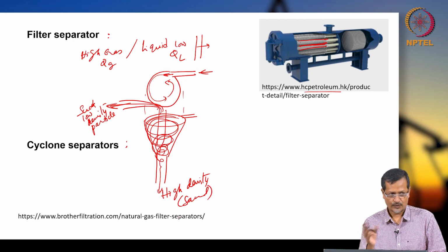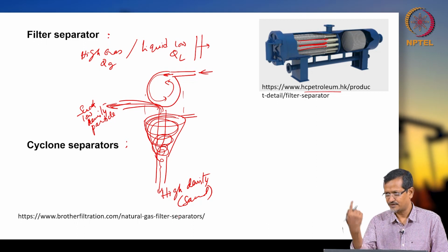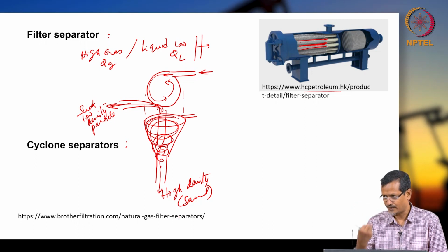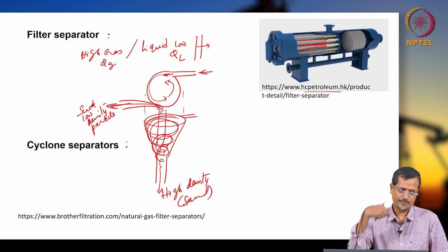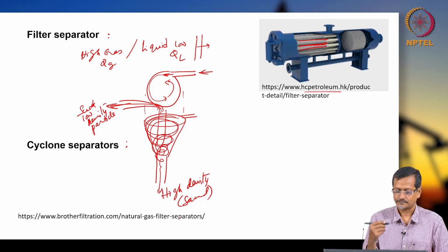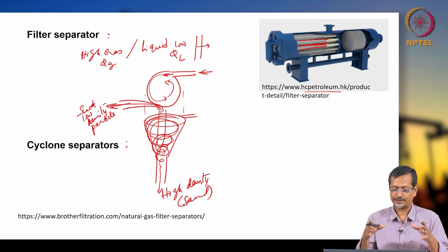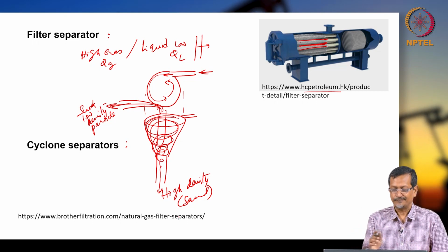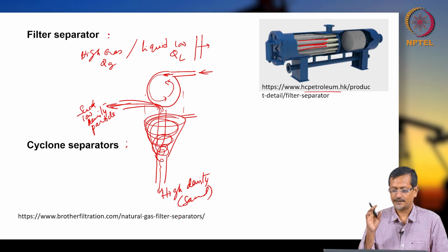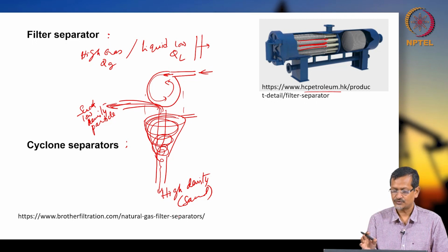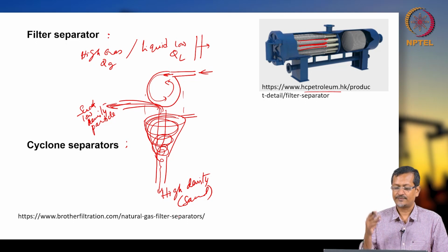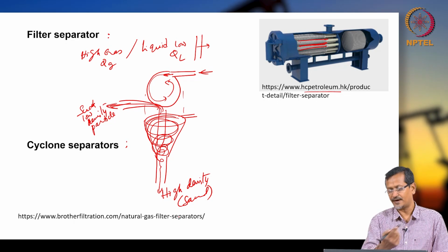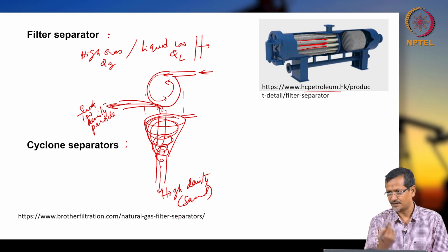or you have an oil water mixture also, where you get very high centrifugal action. So in that case also, high density means water may be falling down, and low density oil will be moving up. Okay, so you can create a separator also using this cyclone, and you can separate oil and gas. Okay, one is that the wellbore fluid pressure is high, so use that directly. If that pressure is not so high, then you can use some centrifugal pump, again you give high pressure and high velocity and it can be separated.